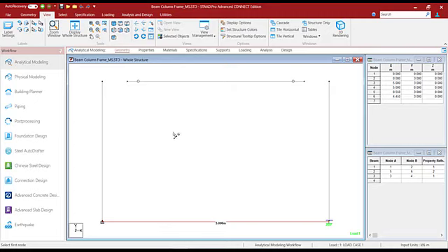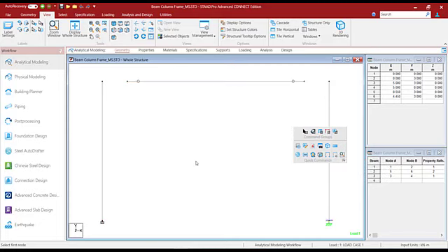However, in this case, the beam has not been defined from the center to center of the columns. Instead, it appears that the beam is dangling in the middle, and if we see the distance from the start of the beam to the end of the beam, it is 3.9 meters. So at least for the start, we can say that the dimensioning here represents exactly what is in the real field condition. Now, let us deactivate the dimensioning view and the support view so that we can have a clearer view of the model that has been defined.